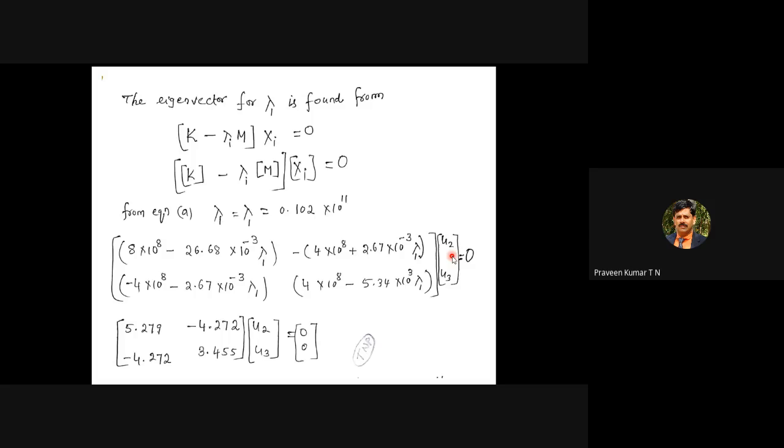But when you come to dynamic analysis, the cantilever beam moves up and down. You have done some experiments in your physics lab also, using the maximum transverse displacement of the cantilever beam. In machine design 1 or machine design 2 also, there is a set of equations for the maximum displacement at the tip of the cantilever beam. That equation gives only the static deflection value, not the dynamic deflection value. In dynamic deflection, the displacement changes with respect to time. Vibration means your displacement changes with respect to time. If there is no change of displacement, then it comes under static analysis.